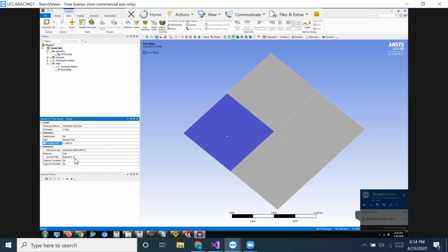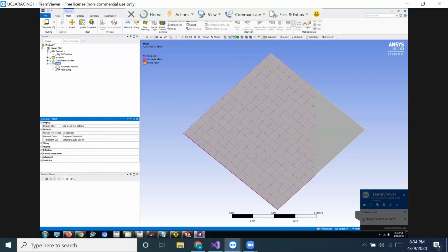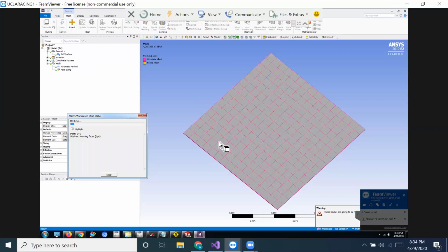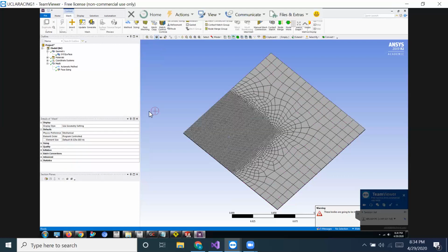After this, we want to pretty much call it. So that's the end of it. So we're gonna generate mesh, and so remember, this is the purple one, is the old mesh. We're gonna see how it changes. So usually this part takes a while. So if you can see here, generally the outer edges where the automatic method was left alone, pretty much left unchanged with some slight changes. And then as you get here, you can see that it changed a lot.